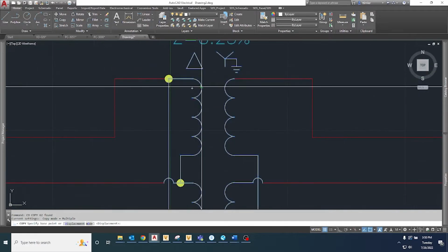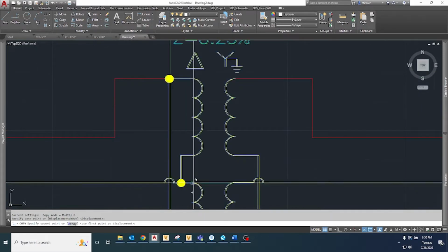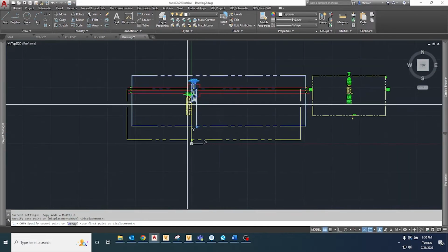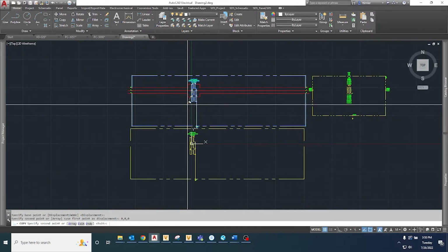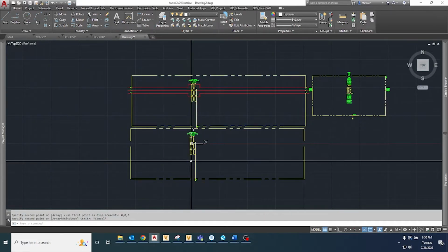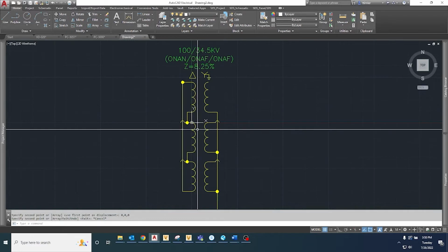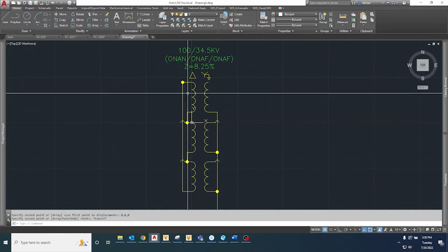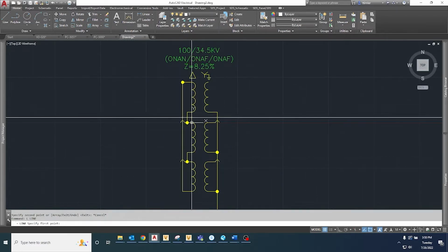You can simply place geometry into the new drawing, decide on an insertion point, and place attributes how you would place them. Our symbol building standard requires the connection point attributes to be on grid snap points. Our grid setting is a 1/4 inch with a snap setting of a 1/16 of an inch.